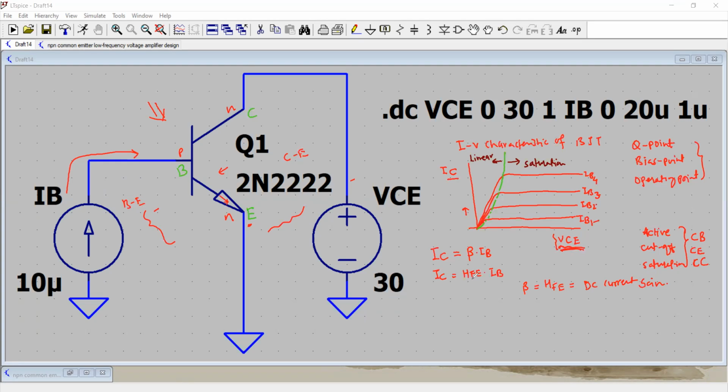Okay. And for a given transistor, when you design a discrete circuit, in the manufacturer datasheet you will find the value of beta. In a moment, I'm going to show you that. So that beta value is your gain. For example, if beta is about 200, which is the case for this transistor part, the 2N2222 from the manufacturer, I will show you in the SPICE model that the value of beta is 200.